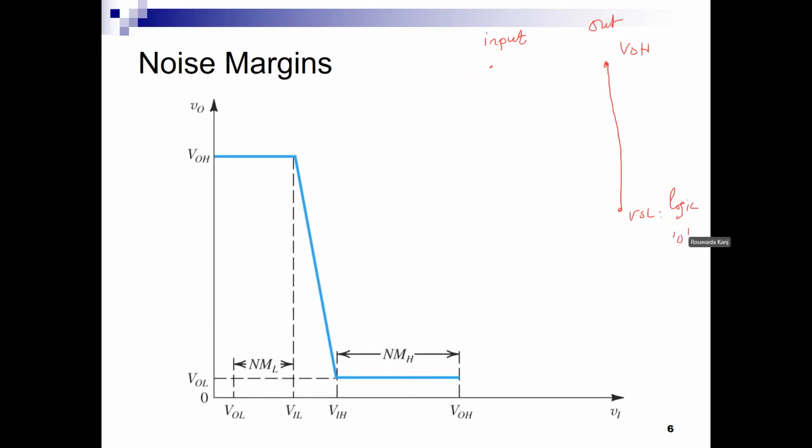And this one is logic 1. Then we said, okay, if I want to get an output which is logic 1, because that is what my sensor or the other devices will capture, let me see how far I can have my input fluctuate beyond VOL to give me this output. If I go as far as VIL, I will still map to the same logic output.